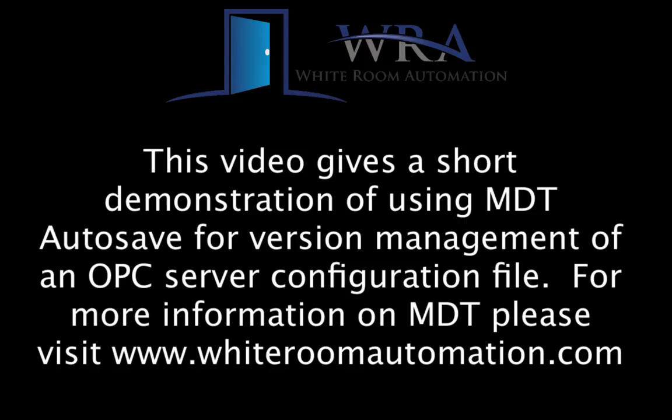The configuration of your OPC server is a critical part of your overall OPC infrastructure, and changes to that configuration can potentially cause significant issues with communications. So today we're going to demonstrate how to use MDT AutoSAVE to keep a history of all of your OPC server configurations and restore back to a previous one if you've found issues.